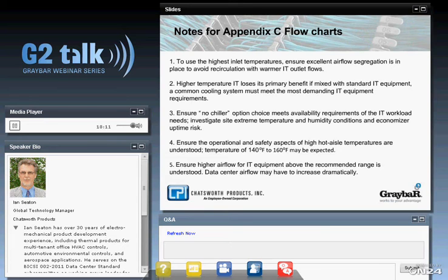The absolute segregation between supply air and return air is required to reap the benefits of anything that we may be doing on either one of these 3 decision trees. Second point just basically reminds us that the data center has to operate to support the needs of the weakest link in the whole chain. So if 3/4 of our equipment is A4 servers, but we've got legacy equipment that has to operate at the A1 level, the data center must meet the needs of the A1 servers.